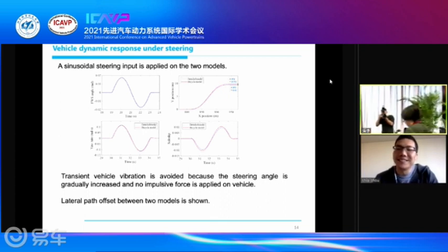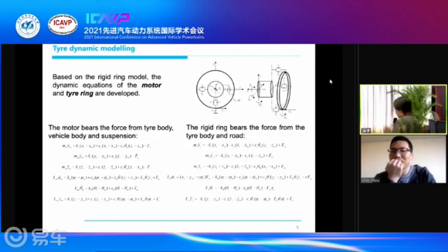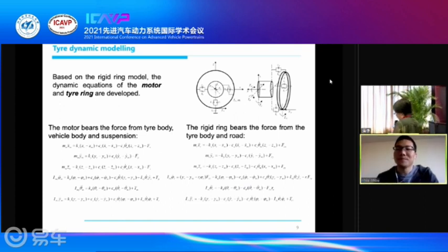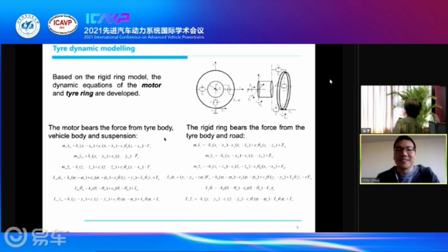You mentioned the tire body. To simulate the tire body, you use translation and rotation springs and damping. I want to know how to determine such parameters as springs and dampings. By test, actually. There is a book named Tire Dynamics and Vehicle, from the magic tire model. They have a huge book. All of the parameters are tested in there. Here we actually didn't test it because we don't have the equipment. The parameters are just published in journal papers or in a book. We just adopt them. We use the parameters of the model directly and compare the difference.